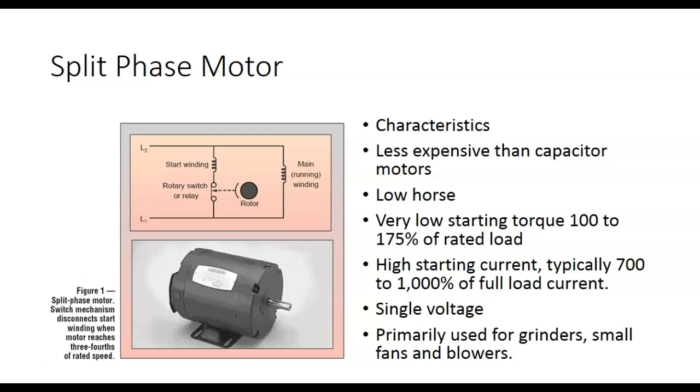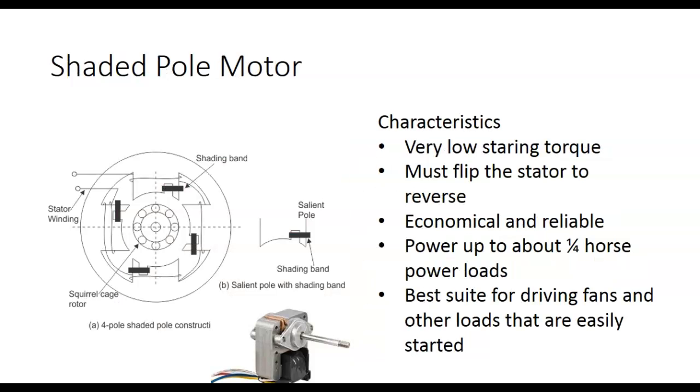How do you change direction? Change the connection on the start winding or the run winding. I'm asking. Do we change the connection on the run winding or the start winding? Start winding. Good. This is a shaded pole motor. We looked at that.